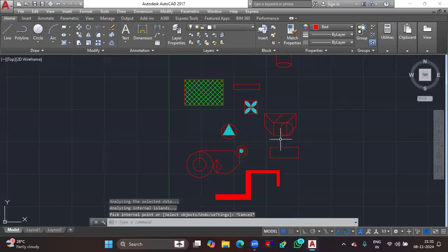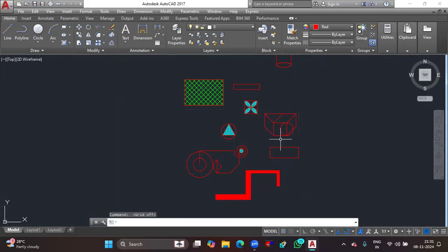So today we learned the introduction to this CAD software, and we learned about the draw commands, especially the F3 function tool, the F8 function tool, and one more thing, F7. It is not much important though. That is the grid mode. If you turn on F7, the grid is on. If you turn off F7, the grid is removed from the view itself.